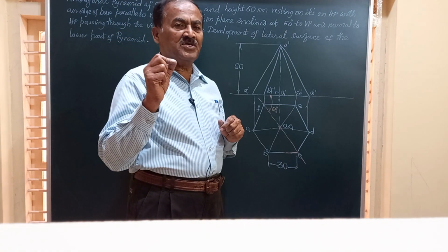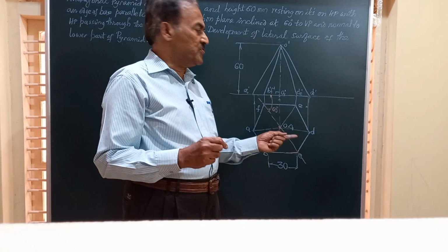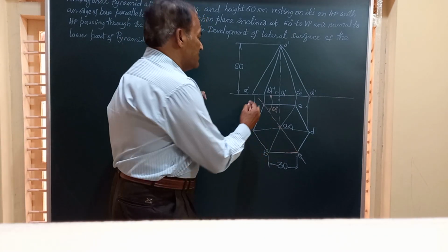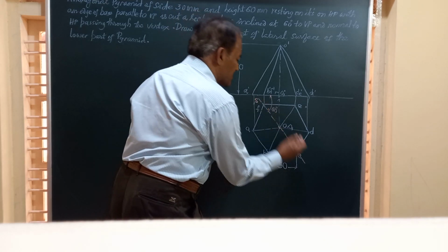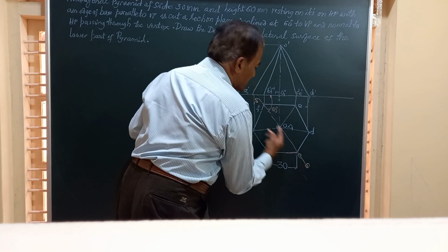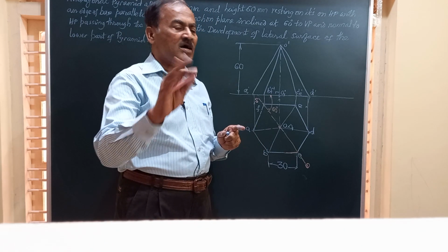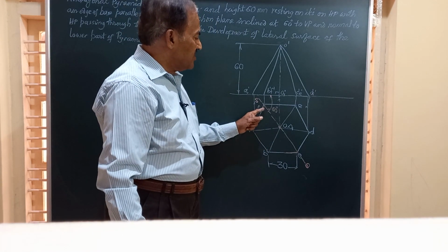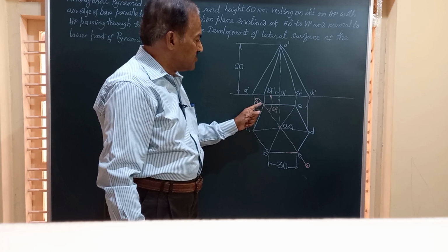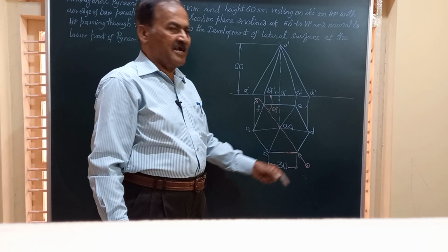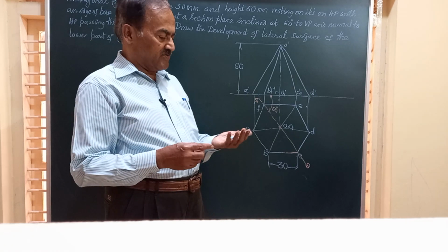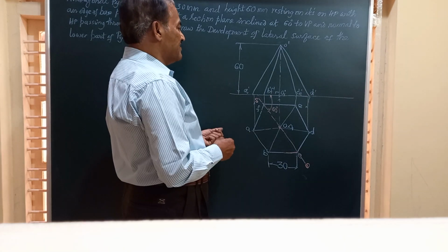And in this construction of the top view and marking of the section plane SS, say the section plane is SS, which is passing through the vertex. If the construction of the hexagon is not correct, then you will not get the section plane passing through exactly this corner and this corner. So you should be very careful while constructing the figure, friends.